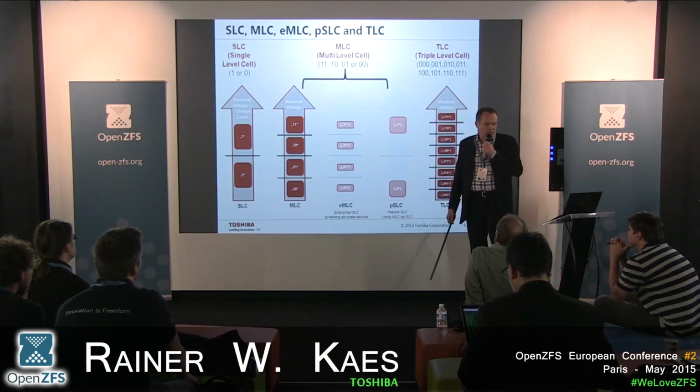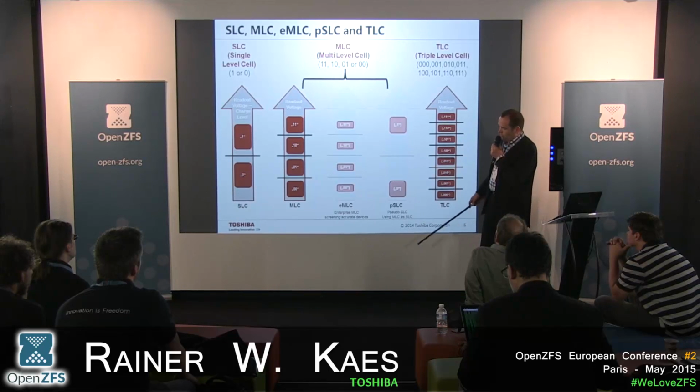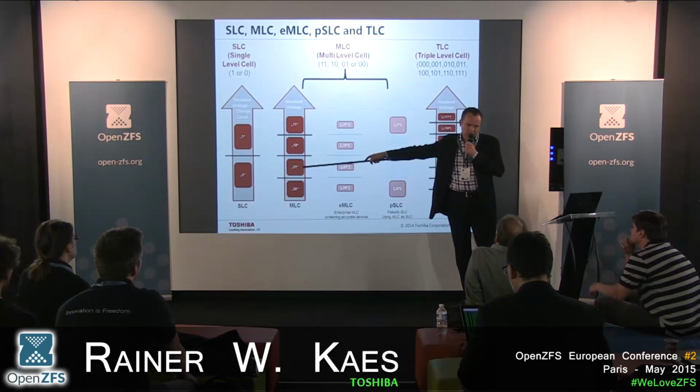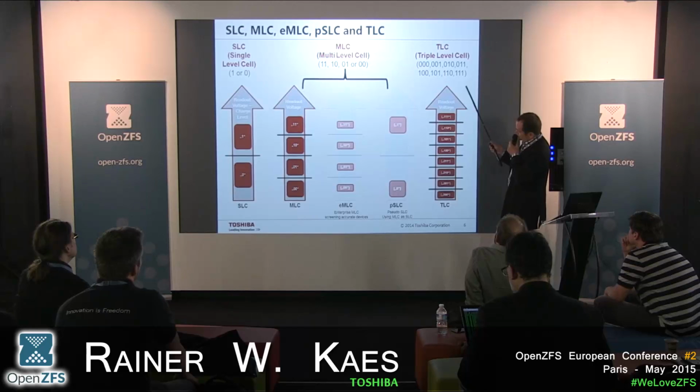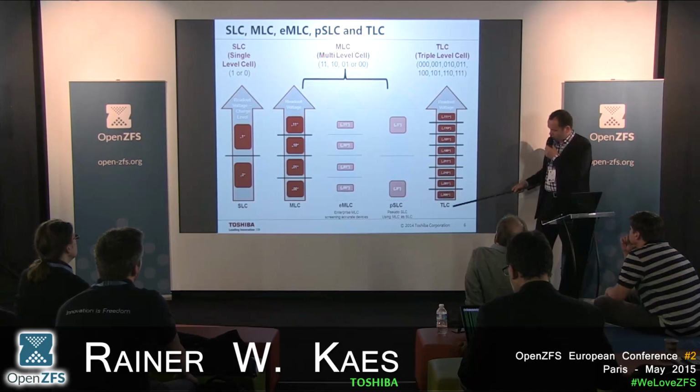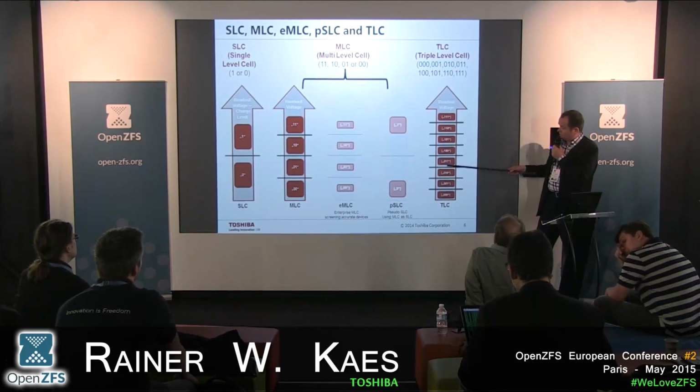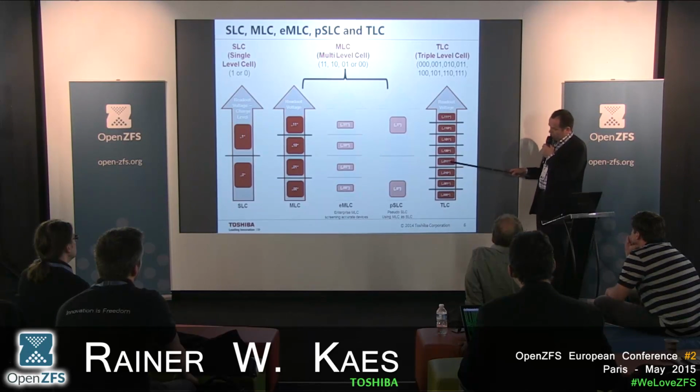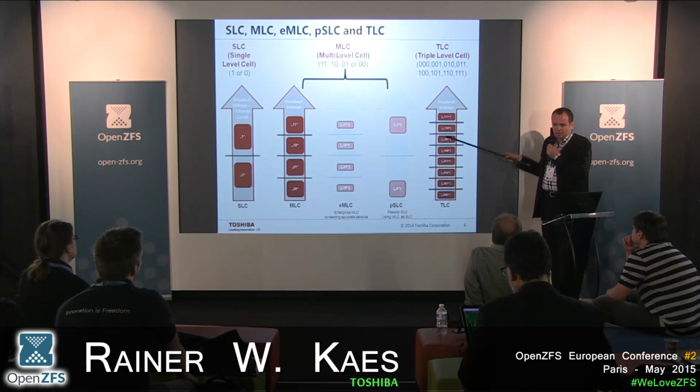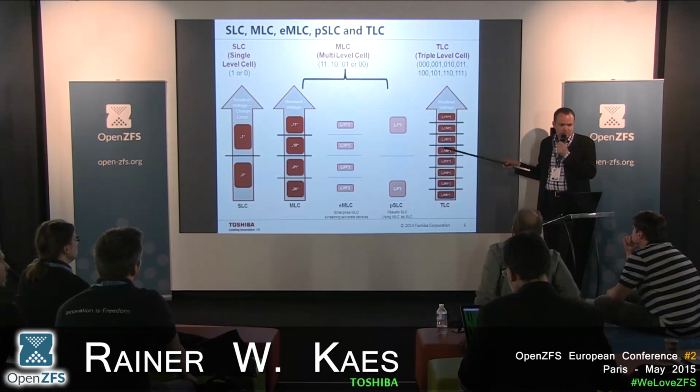For terabyte SSDs, we need to put even more bits into one cell. And this is what we call the triple level cell. So here we are coding no charge, full charge, 7/8, 6/8, 5/8, and so on, to code this into 3 bits. And here it is obvious that we cannot allow much erase damage, because then we are immediately into the threshold to the wrong value, which is fairly small.